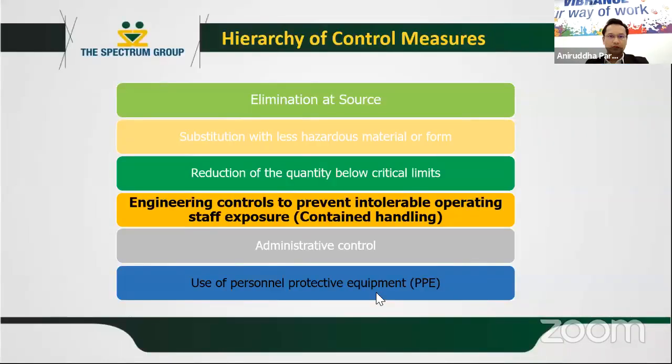So this is like something like a hierarchy of control measures. Typically, any kind of product, say even the high potent product, the primary thing is you use personal protective equipment. But is it the right way? It leads to a lot of operational requirements, operational safeties. You have containment, you have the contamination spreading throughout the rooms, and you are actually virtually making the whole facility contaminated, and then the control becomes difficult.